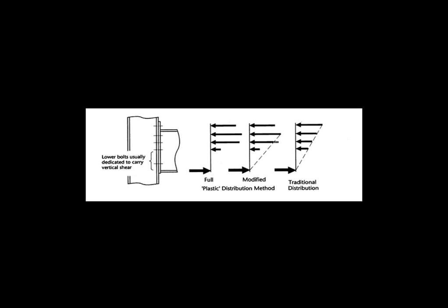Therefore, if one or more bolts reach the yield stress, then the computation redistributes the tensions from the bolts that have yielded to those that still have not. If all the bolts have yielded, then the load exceeds its allowed limit, and convergence is not possible. In this case, the bolt layout cannot sustain the forces applied.